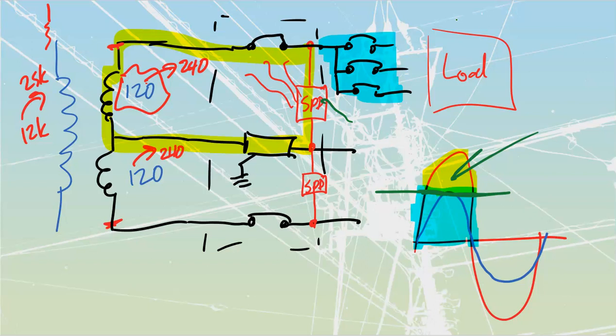If that strikes your hydro lines, which are elevated, sometimes the only elevated thing out in the prairies, it's going to run down through that and then scatter across our grid. It does attenuate as it gets further through the grid because every single piece of copper has inductance. Remember, our simplest form of inductor is a straight piece of wire. So it will choke itself off, and it won't travel forever.